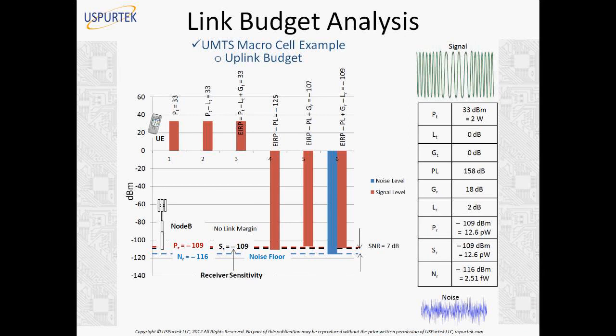We could follow one of those approaches: either reduce the cell size, or increase the transmitter power, or make the handset more sensitive to weak signals, and so on, and then see what is the most economical and cost effective solution.